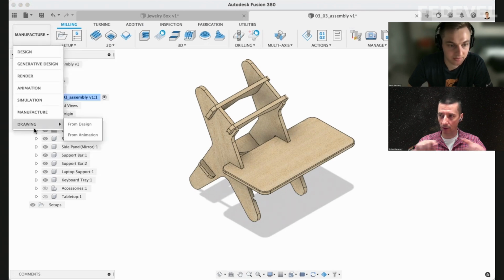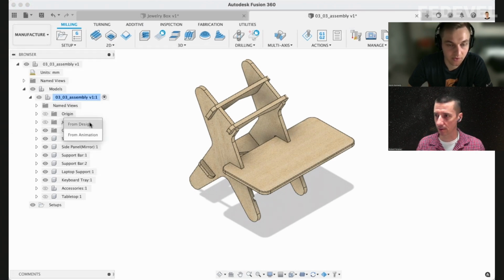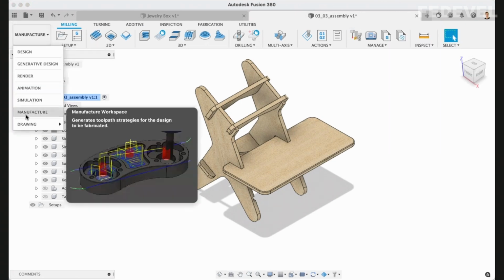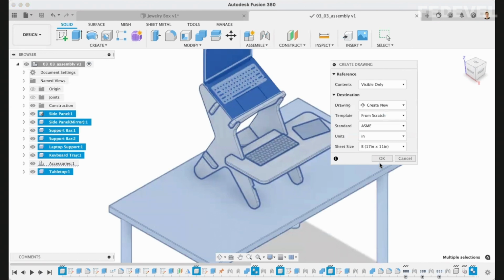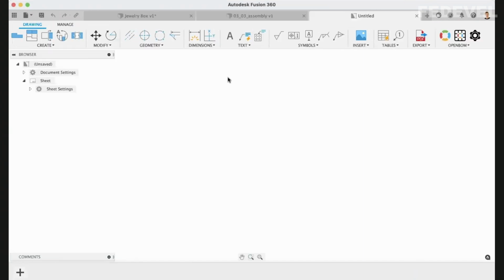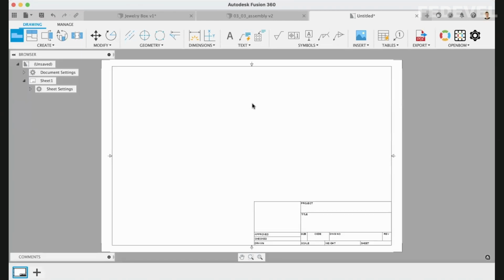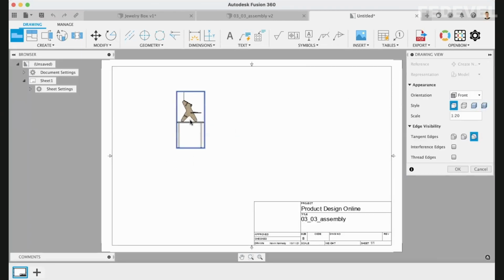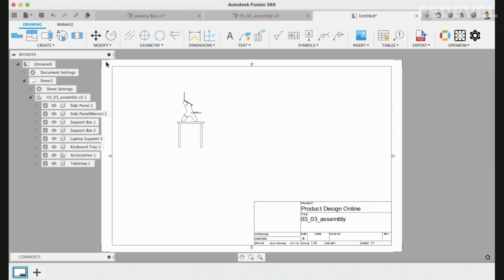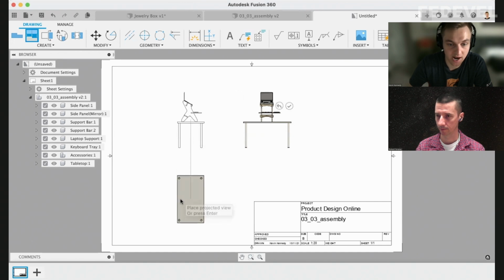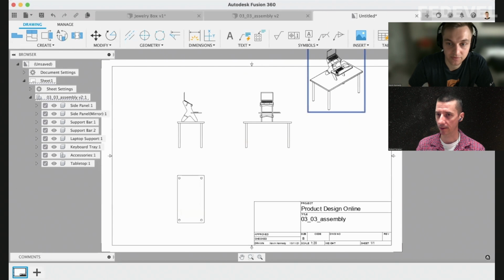These are the standard drawings, with dimensions. I'm just going to skip all the settings here to create it, for the sake of time. Once this generates a 2D drawing, you'll see that we have our flat drawing sheet and then we can place our base view. Once we place that, we can go ahead and create our projected views and really create our 2D orthographic drawings, as well as an isometric view for the sake of showing how this would look.